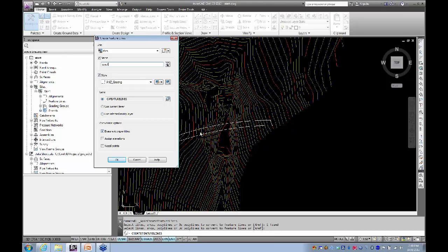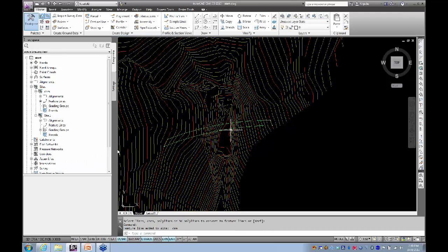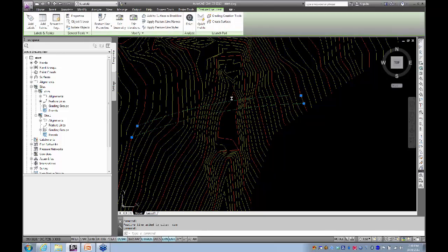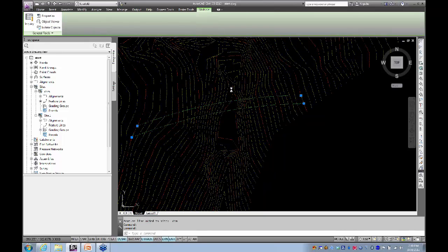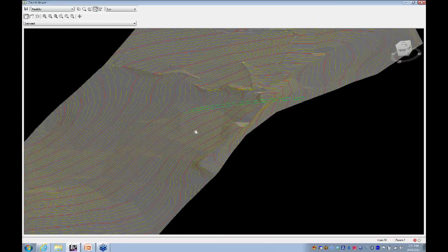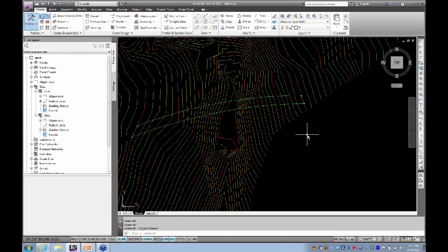We're going to erase the polyline, which would be nice, so we don't get two objects over the top of each other, and we'll go OK, and it just turned green colour there. So whenever I create anything in Civil 3D, in a 3D sense, first thing I'll do is flip it up and have a look at it in the object viewer, and I can see that my crest is there at the levels I was intending. It's above the surface. I'm all happy. So that is good.